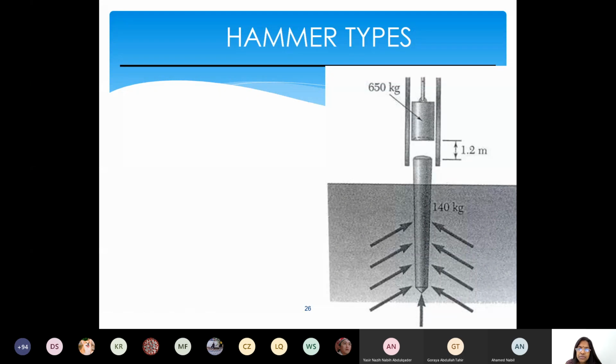You studied three principles in fluid mechanics, right? One of them is used here to drive the pile inside. You shoot the gun. You have studied examples of shooting a gun. By what? Conservation of momentum. Fantastic, very good answer. Momentum principles and force momentum principles, right? So the net force acting on it will be equal to the change in momentum, M into V, right?